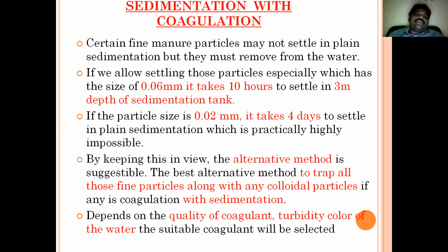There is no alternate way to overcome the problems associated with time duration, because a 0.06 mm size particle takes 10 hours to settle in 3-meter depth of sedimentation.